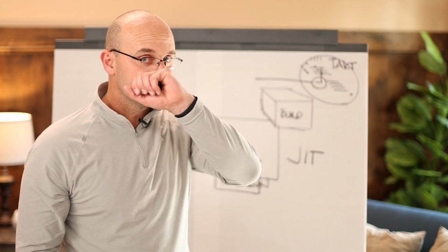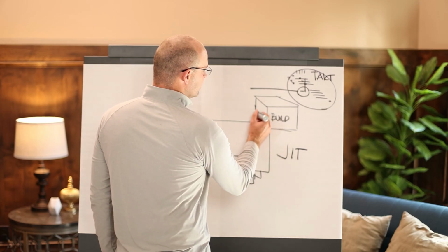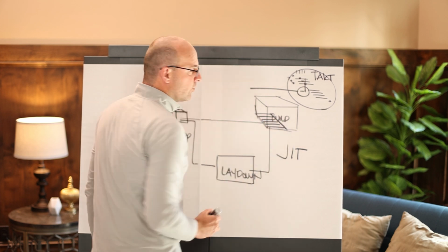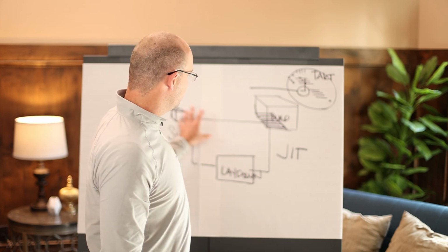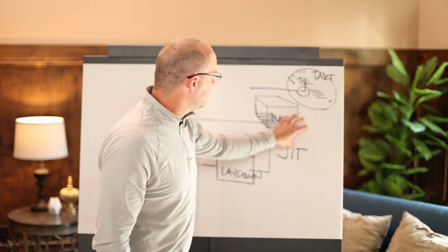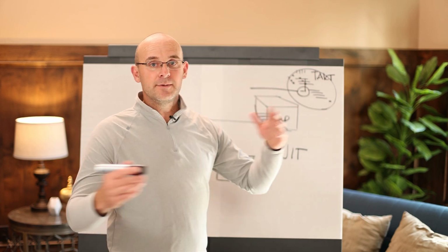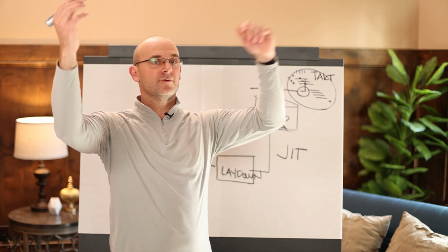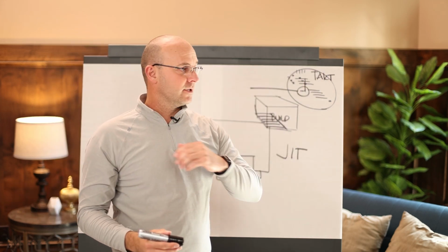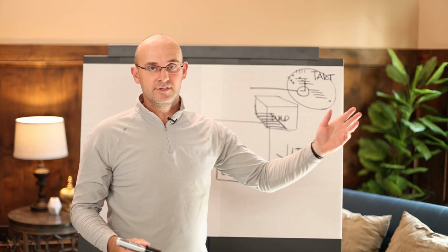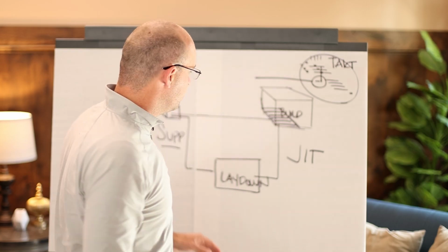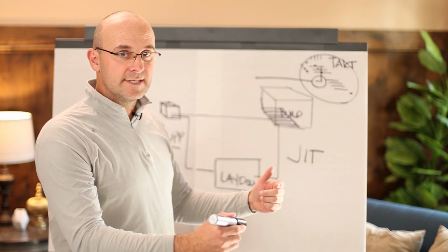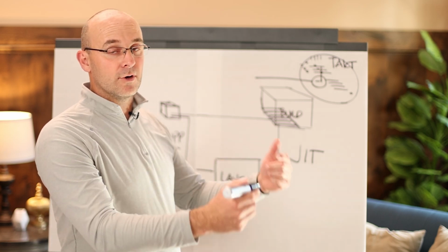The main two concepts here that I want to explain is that if you have a zone inside your building, you don't want to stage that zone before work is ready to go in. And you especially don't want to order all of your materials and stage it throughout the whole building and put it in people's way. If you're ordering duct for 40,000 square foot floors, 4 stories, we don't want all that fire sprinkler pipe or all that duct or all that drywall staged. That's not just in time. Just in time means that we've ordered it to be at the place of work just as it's needed according to that zone, according to that tack time, or according to that duration.